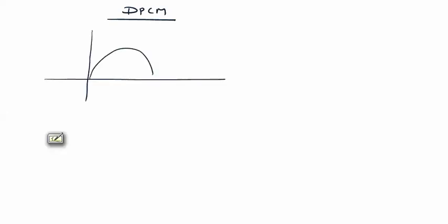Now we will discuss the DPCM, differential pulse code modulation. In DPCM, instead of transmitting the complete sample in a cycle, as in PCM, we are now transmitting the difference between two samples. In PCM we consider each encoded sample independent of the others, with no correlation.